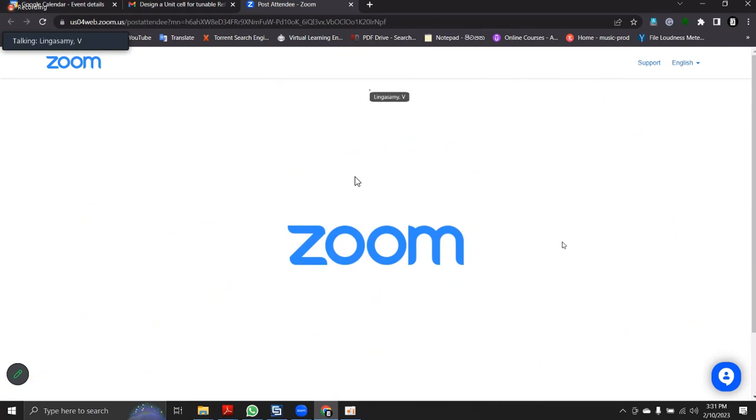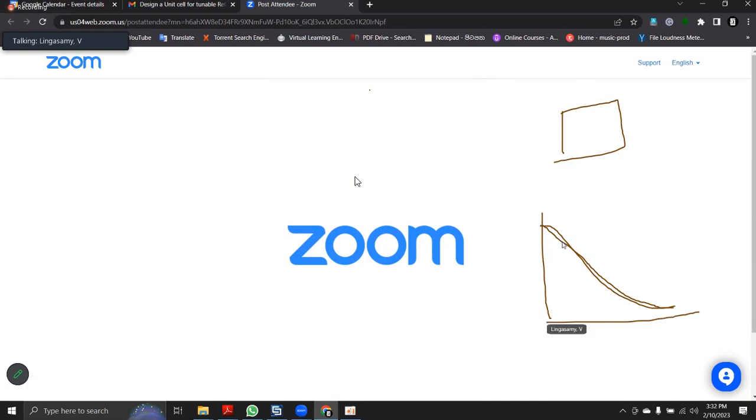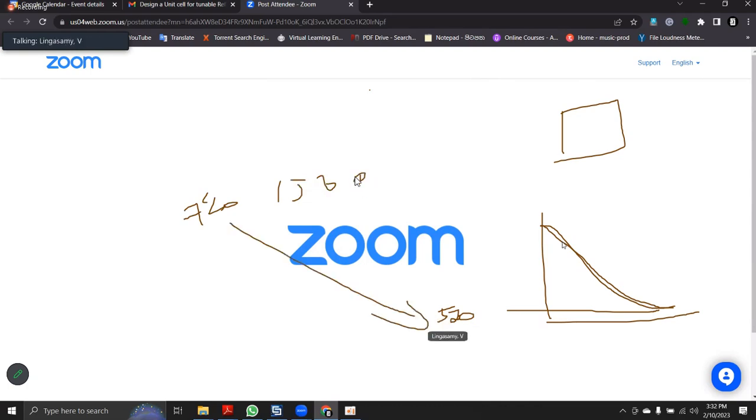That's why we are expecting a unit cell to offer that much phase, for example 720 degree or 520 degree. But we cannot get 720 degree directly, though we can normalize the phase. For example, your unit cell is only giving 520 degree, but your requirement is 720 degree or 1500 degree, and so on. So what you will do is normalize this phase with this value, 520 degree.